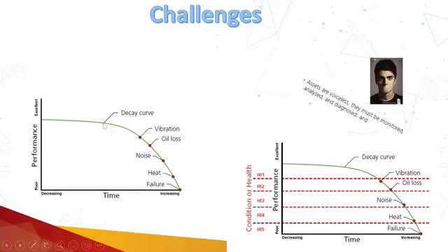So the potential failure has started, but the insulation has not been damaged to the extent that it will cause a short circuit and failure of that cable. So it will follow this type of curve. The start of this decay curve indicates the impending failure or potential failure, and this is the point at which the failure actually happens, and it shuts down the system or the equipment.